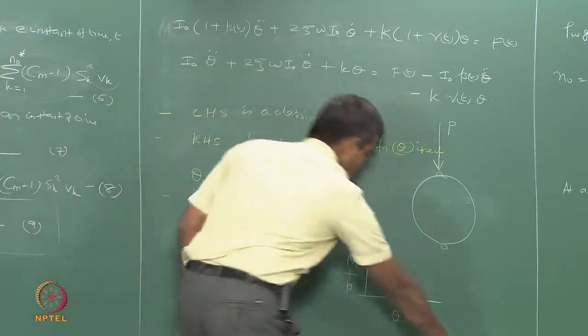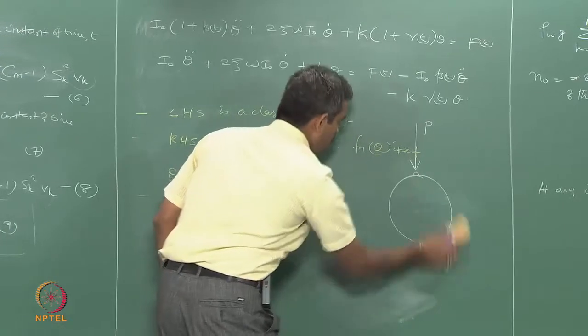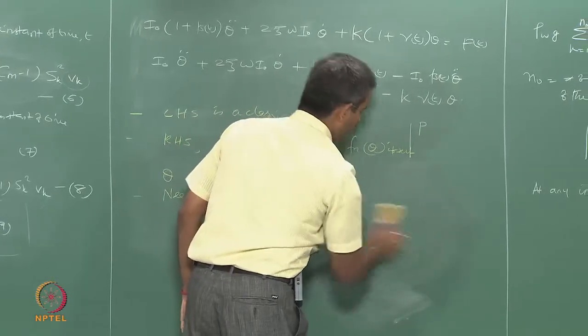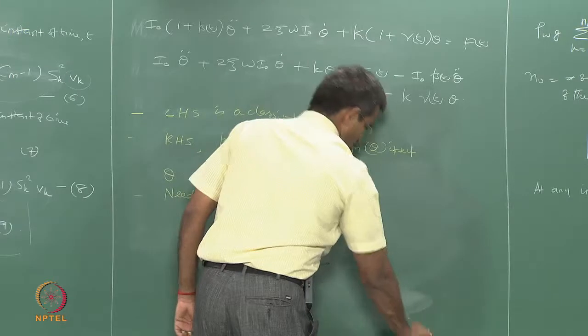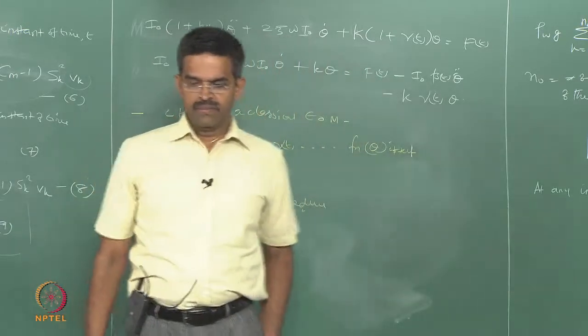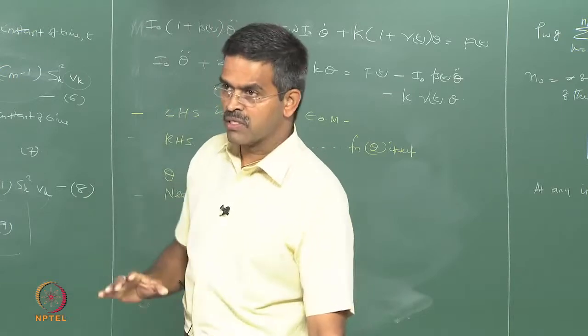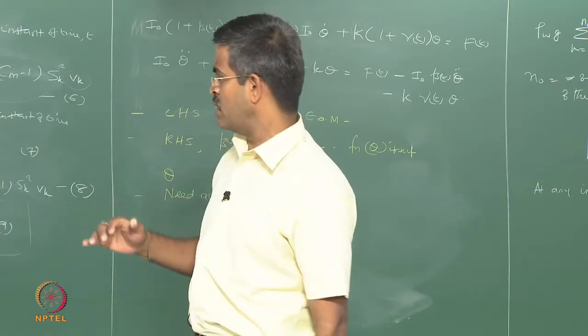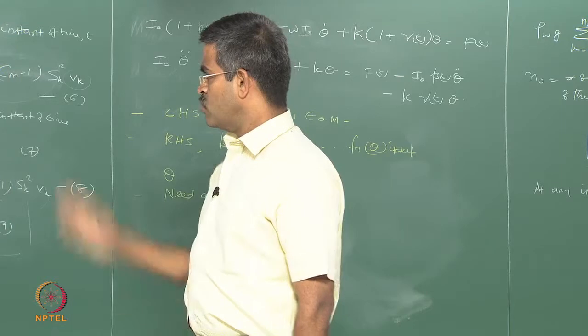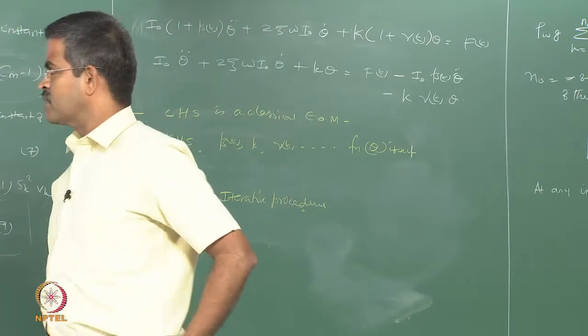That is a very simple idea to understand how the axial load will influence the rotational capacity of the hinge. So, it will offer some constraint because of the load coming on the system. Load cannot be removed because payload is there on the deck. So, use of universal joints ensures that the columns remain parallel to one another.